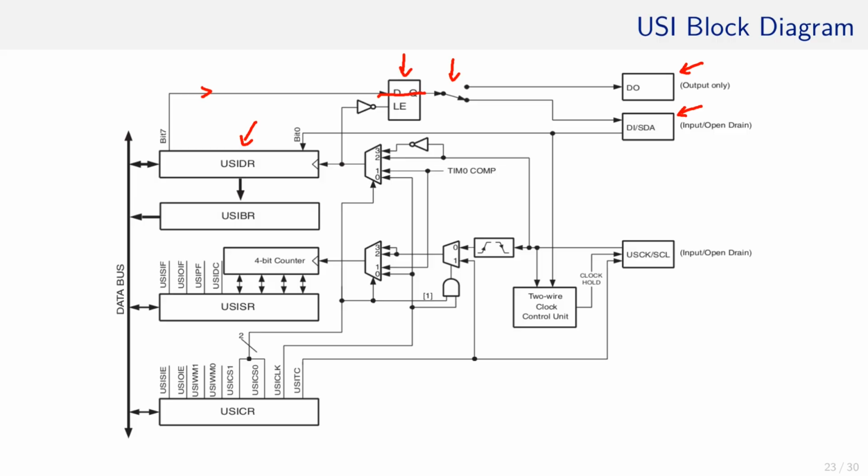In case the output is different from the input for a protocol, the wire is connected to the digital out pin like this. This is the case for instance in SPI, in which MISO and MOSI are physically separated wires, or in UART, in which each pair communicates through a TX to RX pair.